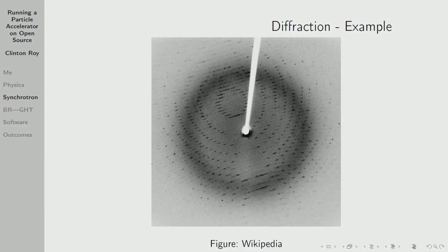We can't let the X-ray source actually hit the detector because it'll burn the detector out. So what we do is we put a little beam stop in the way. Right in the centre there's a little beam stop. It'll only be like 4 or 5 mils of aluminium, and that's where the core of the X-ray beam will hit. And then there's an arm that we can see, which is the white part, which is holding that beam stop there.